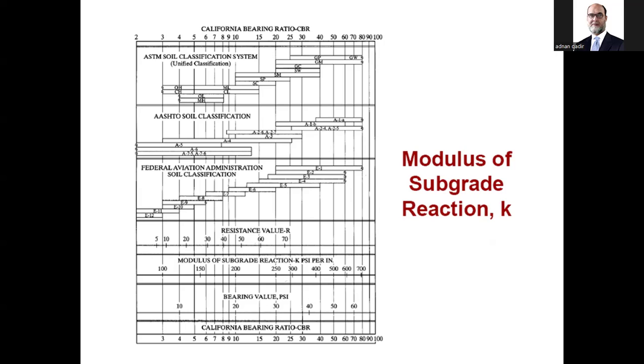So one thing you could say is, I'm not going to design your pavement, go and get the CBR value. This is very rude to some people, because a common man is not a transportation man. He's not a pavement engineer. So while doing the analysis, most of the time people don't recommend that CBR test, unless or until there is a classified highway construction project.